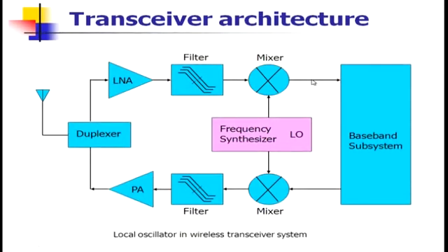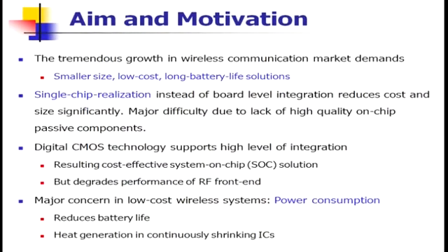After the mixer you have the filters, and the rest is the A to D converter at 100 megahertz to 400 megahertz at 12 to 14 bit, and finally the DSP will conquer the world. So then the digital people will come and shake hands with the RF front end. But the RF front end is omnipresent, right? You cannot avoid the front end designer, because the front end will be required even if you are making a digital-assisted frequency synthesizer or RF front end.